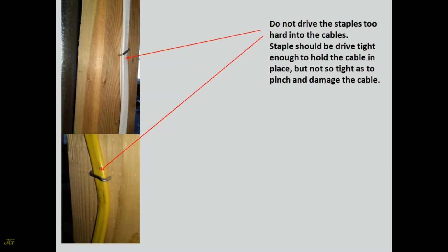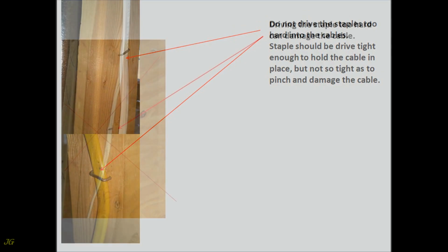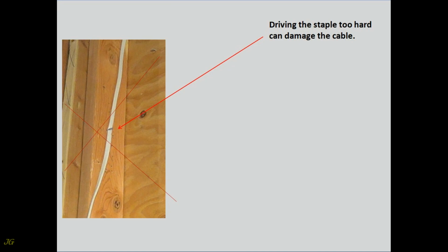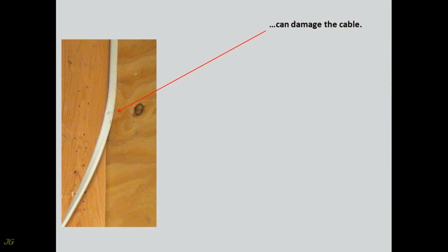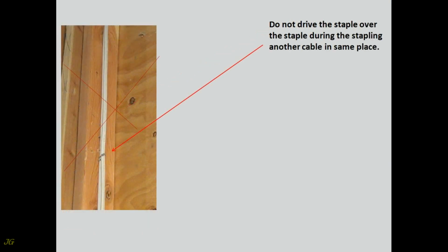Do not drive the staples too hard into the cables. Staples should be driven tight enough to hold the cable in place, but not so tight as to pinch and damage the cable. Driving the staple too hard can damage the cable. Do not drive a staple over another staple when stapling another cable in the same place.